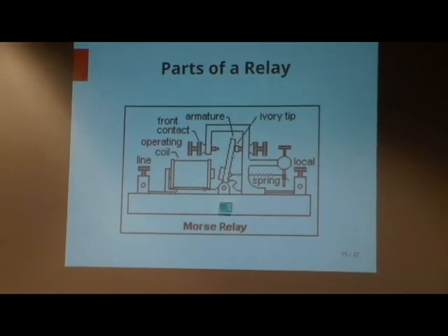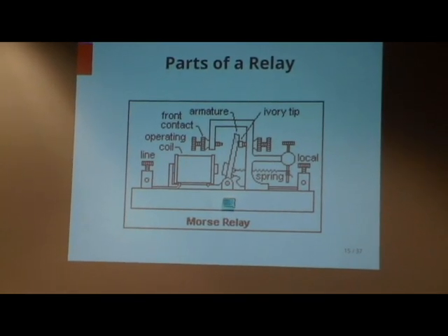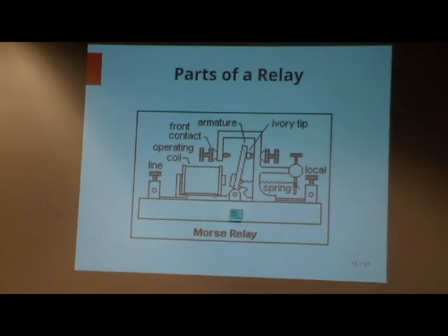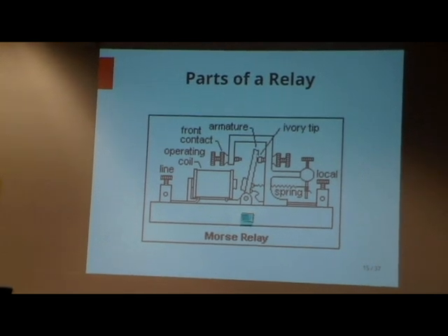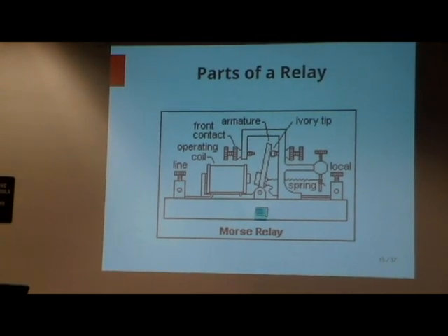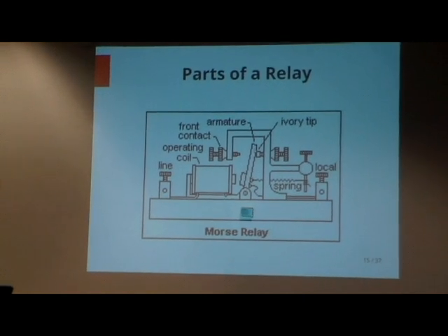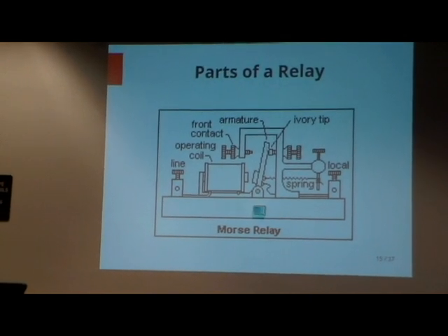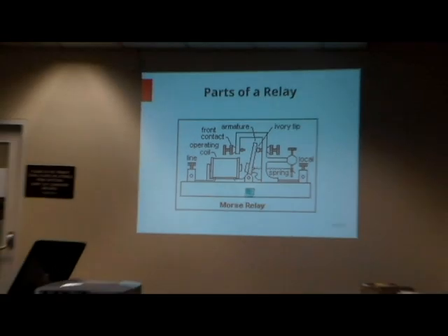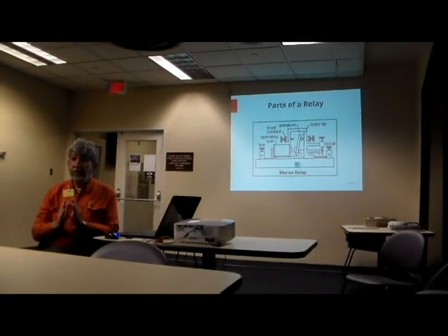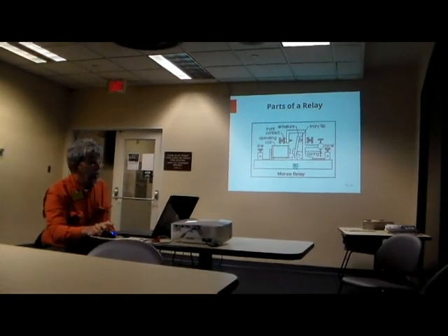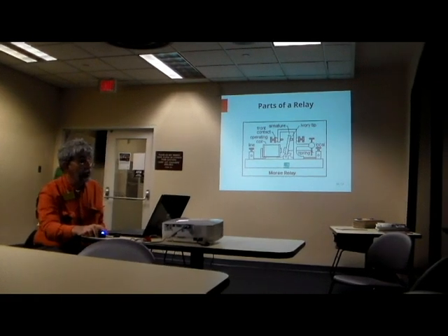So here's your armature, all right? And notice that it's upright and balanced when it's real. This diagram shows a much larger range of play than would normally be used so that you can clearly see things in it. But really, the amount of travel in a relay was kept very short so that it could operate quickly.